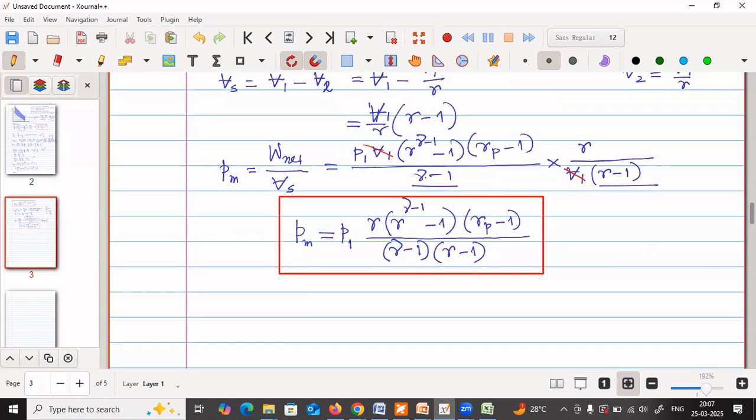So it can be, for example, a simple Otto cycle efficiency calculation. The compression ratio is given, and the particular working fluid, either CO2 or air, is given. So accordingly, you can understand the value of specific heat ratio, and calculate it in one step.